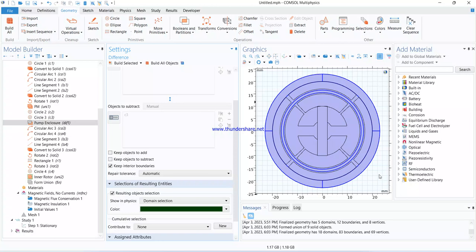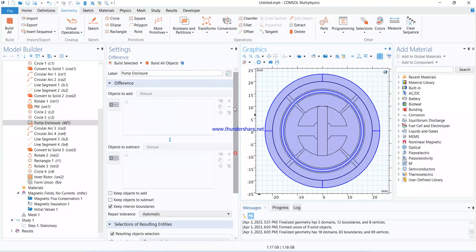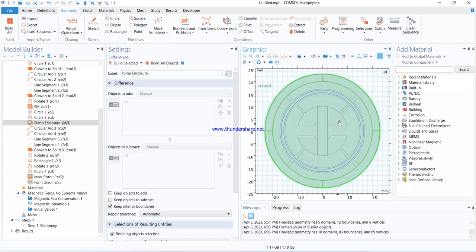Now you can model it as per your own. This I have shown you. I want Vishwa to now give the boundary conditions based on the first lecture and simulate, and show me how the magnetic flux is induced in the inner rotor, because the maximum flux induced in the inner rotor determines how much torque it can give. That is the main key factor.